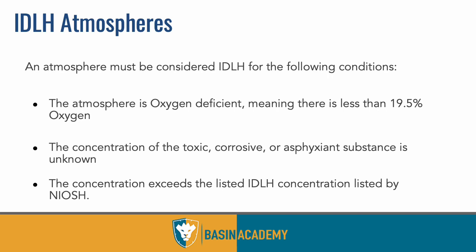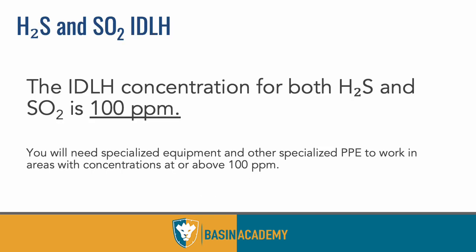It's nice to be optimistic, and I'm kind of an optimistic guy, but when it comes to H₂S, there is no room for optimism. It's all bad all the time. However, and we're going to get into this in a little bit, there is a way to prevent exposure, and we do it every day. This is part of our work scope, so there is a way to prevent exposure and potential harm to your body. So for both SO2 and H₂S, again, the IDLH is 100 parts per million, so keep that in mind.